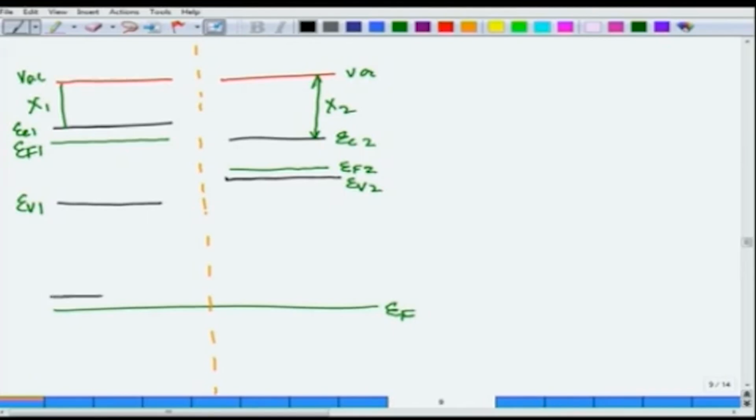So right here I am drawing the same band diagram as up here, and the same thing will happen here also. Far away it will remain unaffected. The EV level will maintain its P type behavior in the same way, and here would be the other level, EC2, at approximately the same distance as before. We are going to draw this.